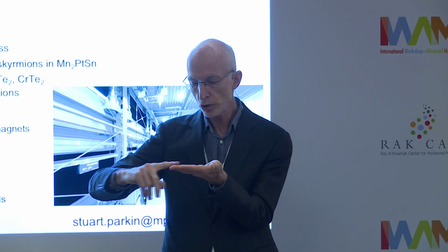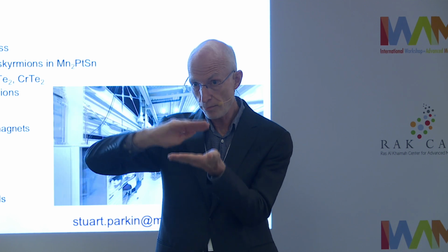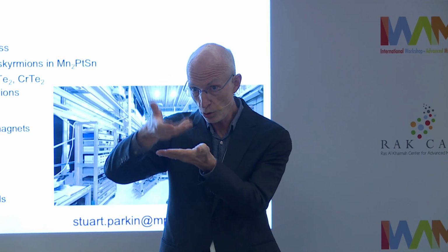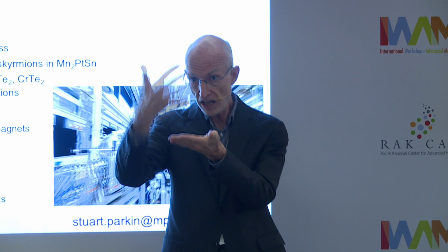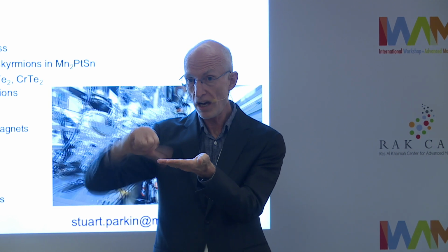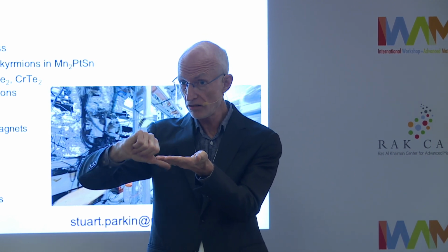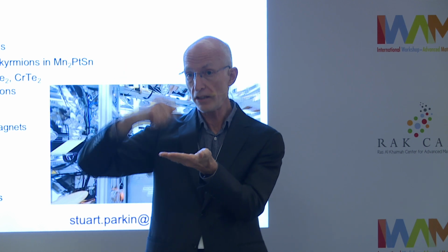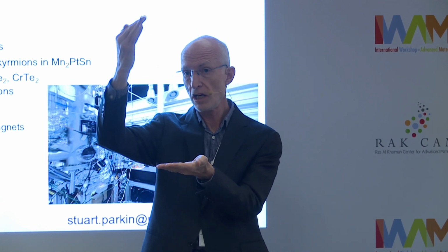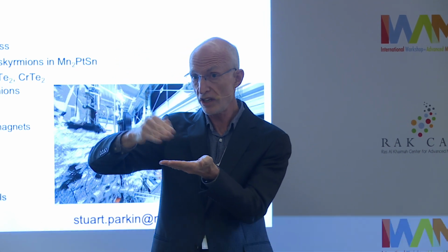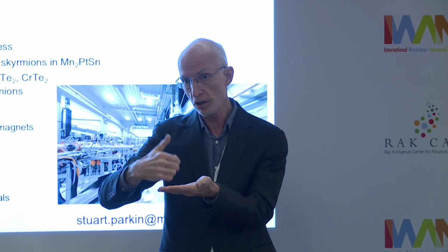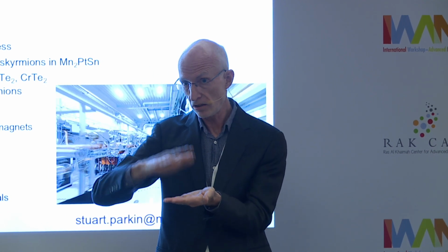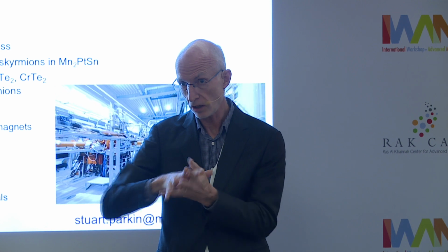So as the domain walls move under that insulating layer coupled to a reference layer, the reference layer is static. The domain walls move up and down, the magnetization goes up and down, and so they become parallel or anti-parallel to the reference electrode. And so the tunneling current that you would pass through that device would be high or low, depending upon the state of the domain in the racetrack. That's how you would read.